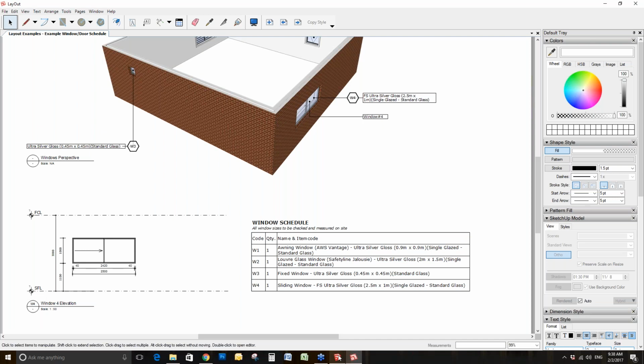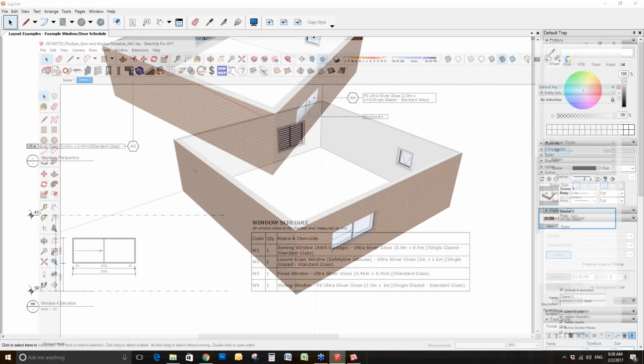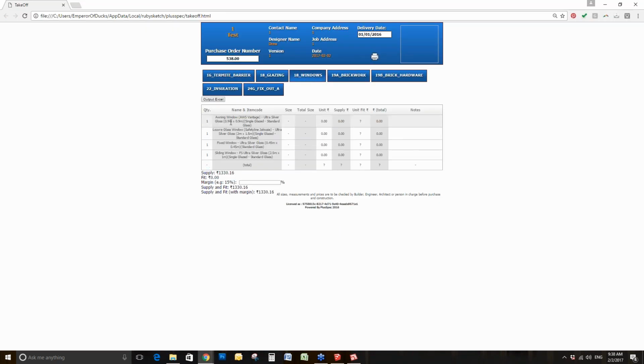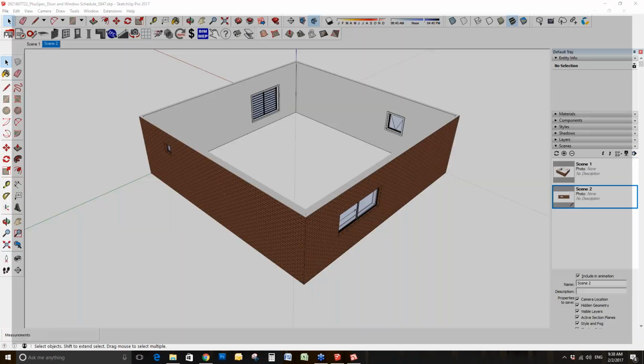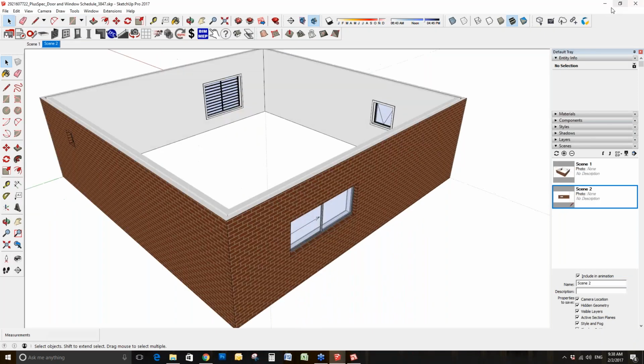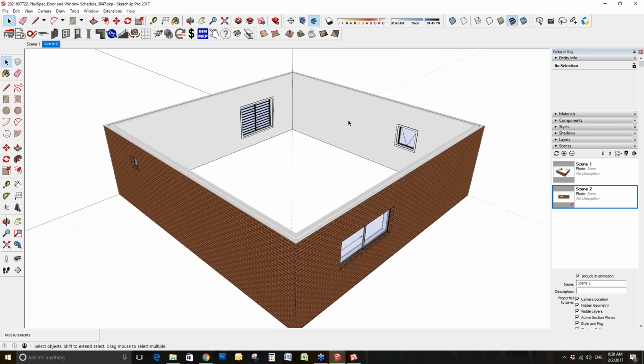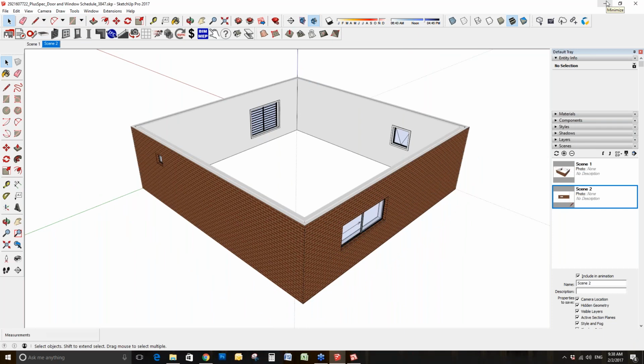it produces the schedule. So again, if I go back into here and I click on the takeoff, it's generated my takeoff. If I click onto my Windows tab, it's brought in all of the information about those windows or doors. That means if I output this to Excel, which I've already done, I can then manipulate my Excel document even further. I can start to capture exacts, numbers, putting any other information in there, whatever I want to do. Then you're saving it as a CSV file. If you haven't done that in Excel, it's super easy. You just, in your Excel document, file, save as CSV.